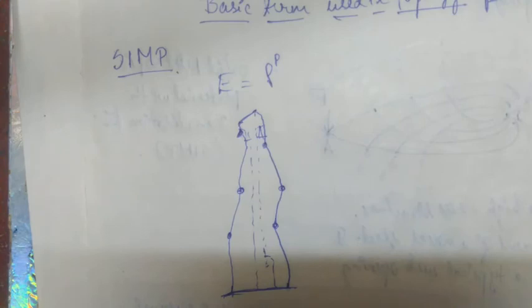The braced outrigger structural arrangement has been selected for the Bionic Tower, whereby the structural core is stabilized by a series of structural elements at the perimeter of the building. The core is connected by external bracing elements or trusses. The braced outrigger was selected as one of the basic arrangements that fulfills the architectural intent. The core is connected with the perimeter columns, as we can see in the diagram, by a series of horizontal trusses.